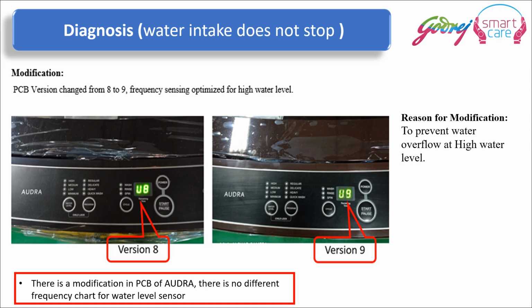If the water intake does not stop, there is a modification which has been recommended. We have to change the PCB version from 8 to 9. Frequency sensing is optimized for higher water level.